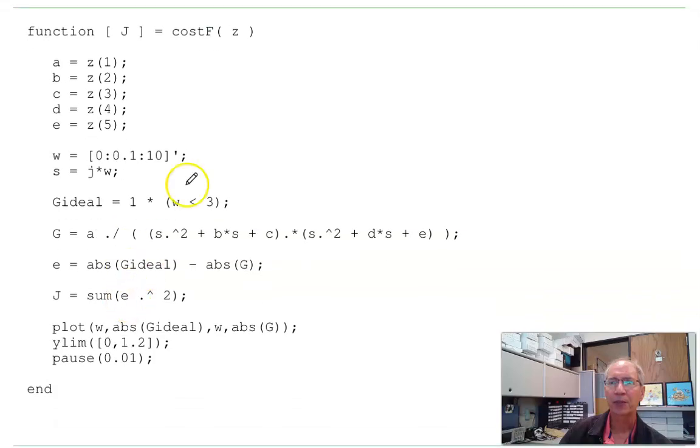So here's the function in MATLAB. I'm going to guess A, B, C, D, E. fminsearch wants just a single parameter to be passed, but that can be a vector containing 5 terms. That's what those 5 terms mean.